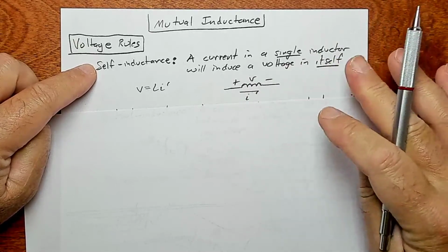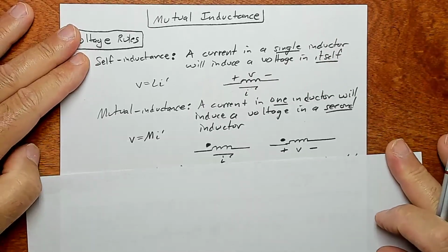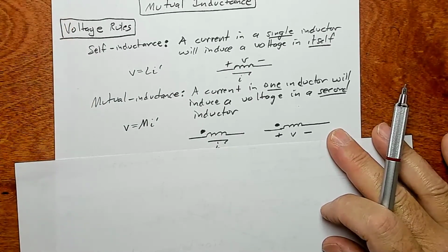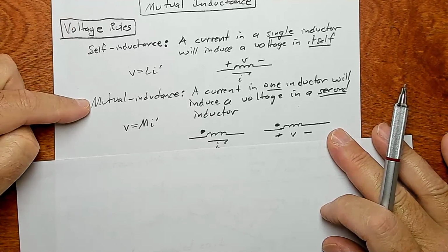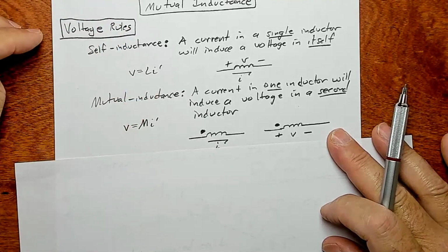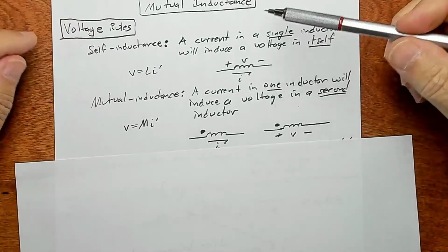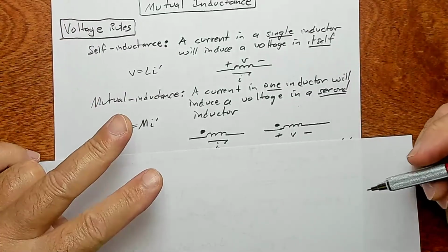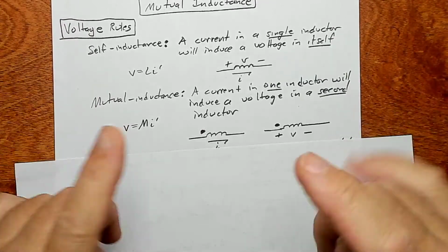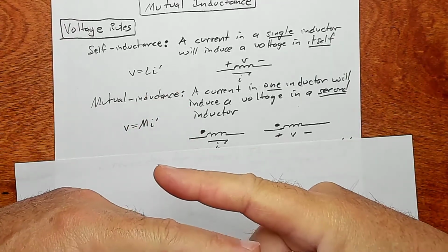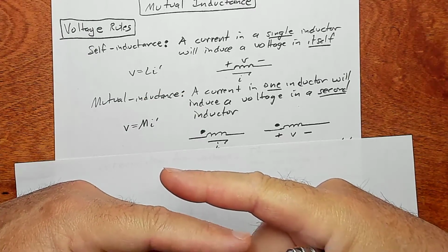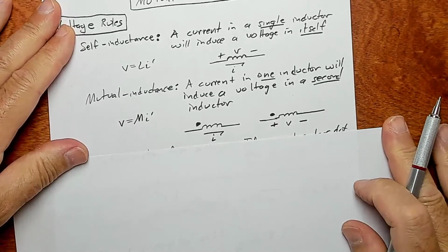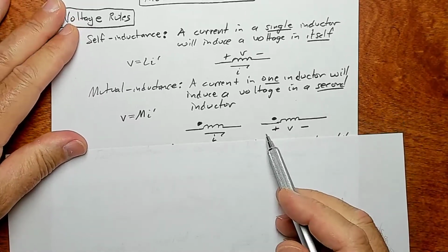That's just regular inductor behavior. But if you have two inductors, then you get mutual inductance, right? So we're going to write equations that have self-inductance and mutual inductance. You've got to keep them straight. Both effects will be present. The self-inductance effects will be there, and then if you have two inductors close together, there could be a mutual inductance effect, and this is the model for that.